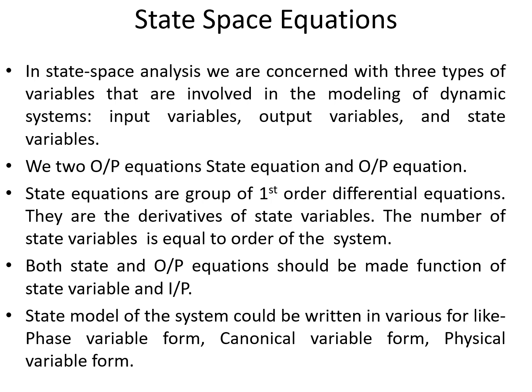State equations are a group of first order differential equations which are the derivatives of the state variables, and the number of state variables is always equal to the order of the system. For example, if the order is 2, then we are going to have two state variables. If the order is 3, then we are going to consider 3 state variables. Both state and output equations should be made a function of state variable and input.